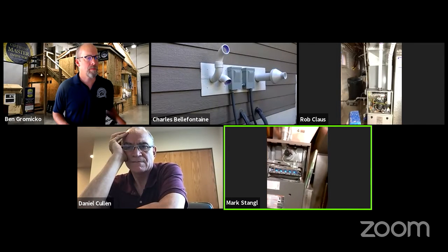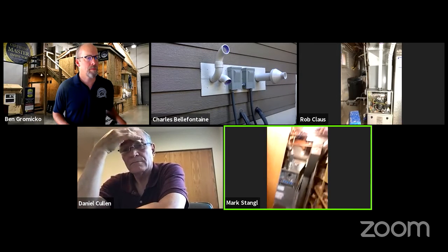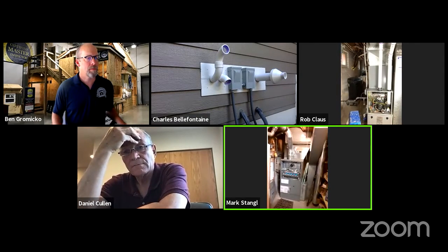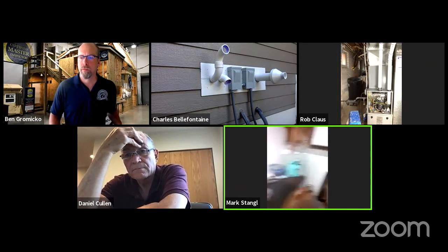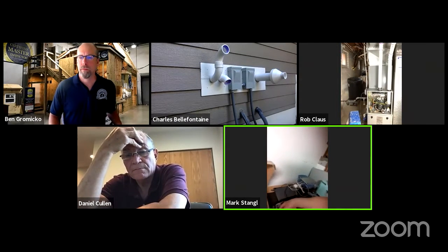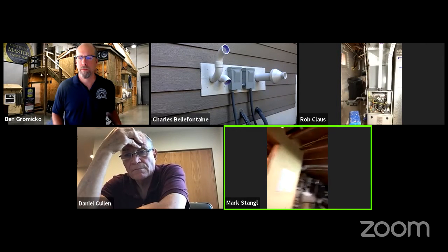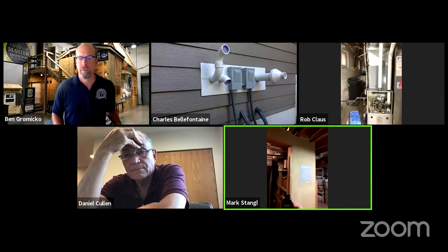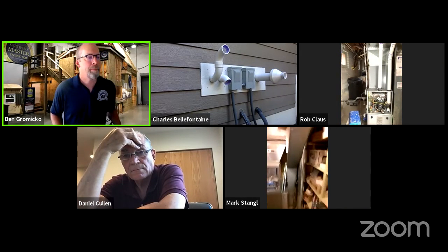Now, one of the next things that I do after I've verified that the flames are operating, burning correctly, and of course, in this furnace, you can check for any dust accumulation or dirt buildup, and I always look for that as well. I have here a carbon monoxide sensor that I use frequently. Can you see this one okay? And I carry this with me.